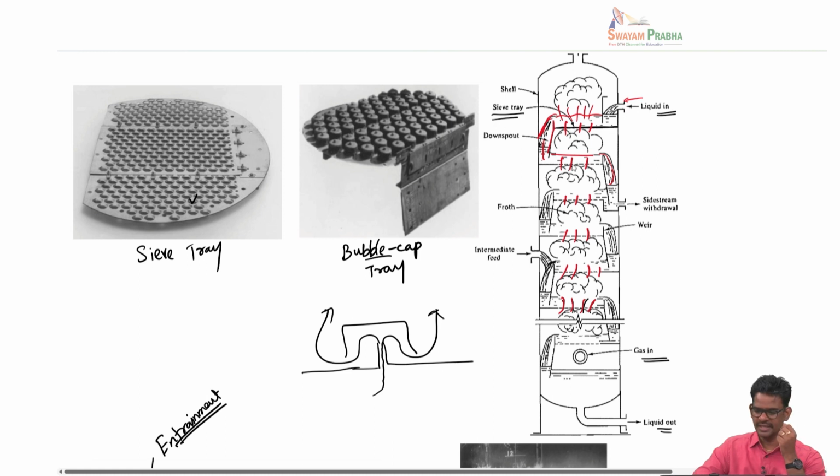Now the inter-spacing of the trays depends on several things. For example, depending upon the nature of the tray, it has to be cleaned once in a while. So there should be a provision so a man can actually enter this column, do the cleaning operation, and come out. So the sieve spacing is decided by considerations other than mass transfer, such as maintenance and cleaning.